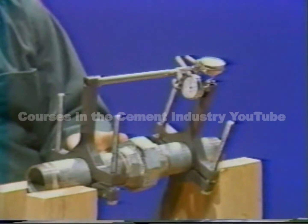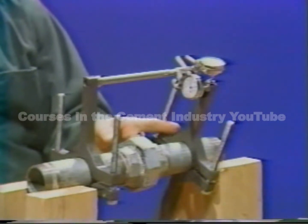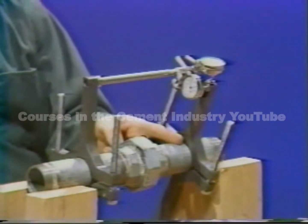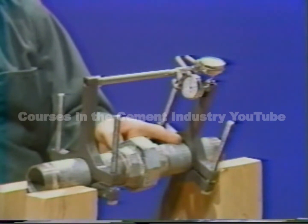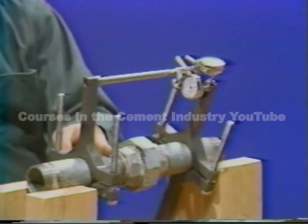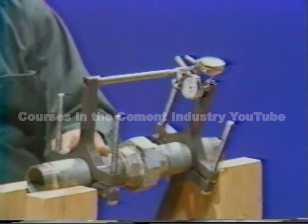Let's start over here. This post is rigidly mounted on one shaft. Because it's rigidly mounted, it will have the same angles and offsets as the shaft. The post is always installed on the shaft to which you will be aligning. The bracket is rigidly attached to the other shaft. The bracket is mounted on the shaft that is repositioned during alignment.